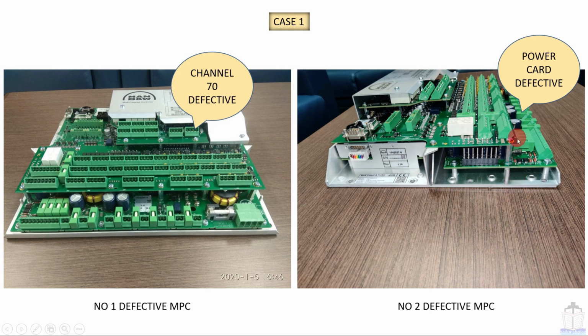So how will you repair this card? Here you can see that this power card is defective, but in this MPC the power card is okay. So what can you do? You just take out this power card and install it here. Remove this power card, take out this power card and install this power card in here. By this you can make this MPC operational. So this one was the first case.